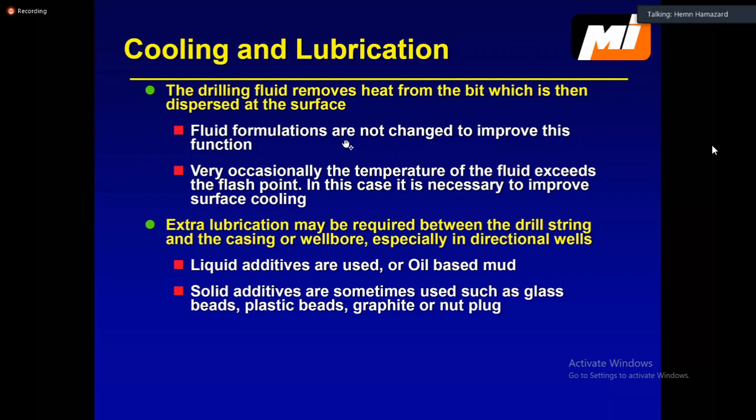And then also when it comes to the annulus, it can lubricate and cool the other components in your BHA, like your stabilizer, like your directional tools, or if you are in deviated holes, because the casing is like this, and your drill pipe and the entire string also is like this, so it's not vertical, it cannot stay in the center. Of course, your drill pipe is having friction with the casing, so that's another case. Cooling and lubrication of the mud is important.